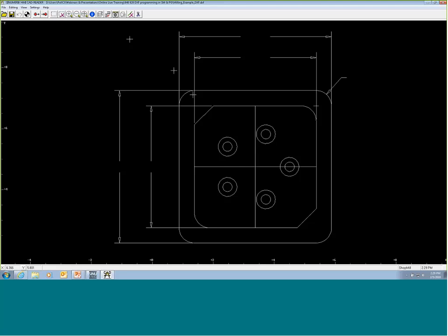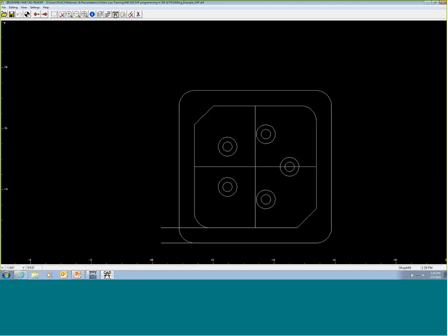So we want to use this one little icon right here that looks kind of like a scale and a circle. And what it's telling me in the bubble is that this removes any dimension lines or hash marking in the part drawing. The software determines what it feels is a dimension line or a hash line, and by toggling this, it suppresses them. You're going to see as we go through, we're going to modify and change around the drawing a little bit.